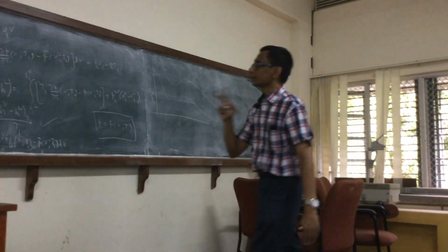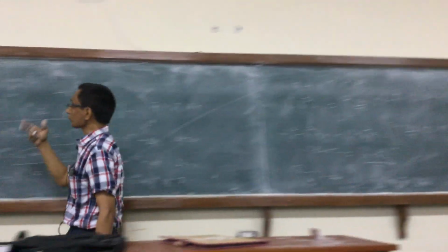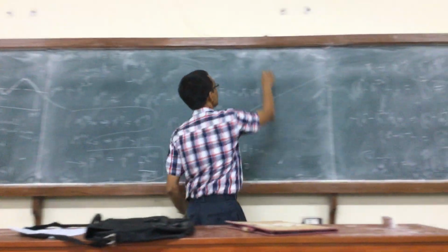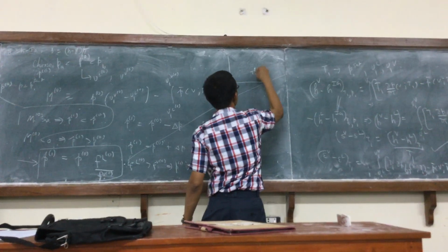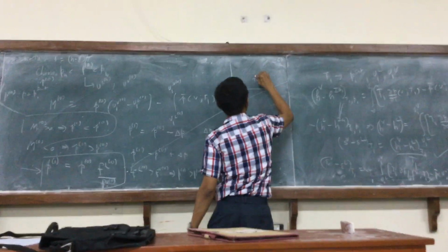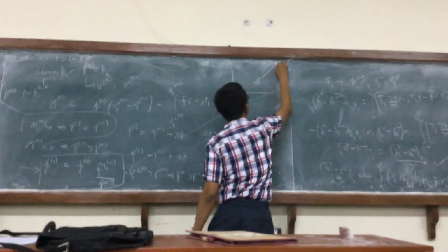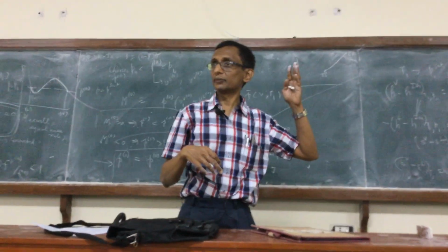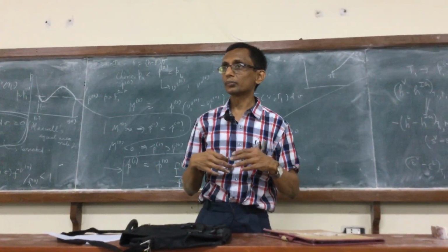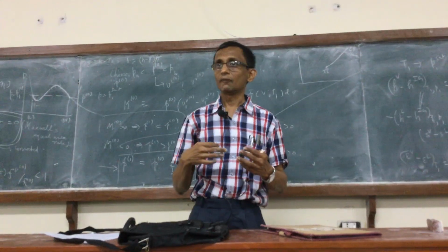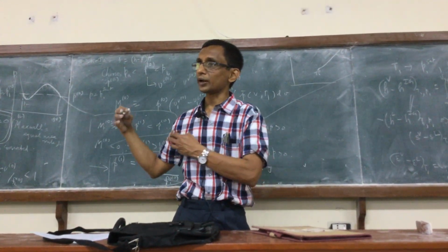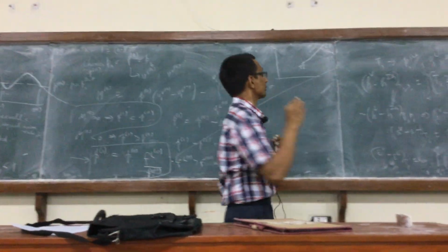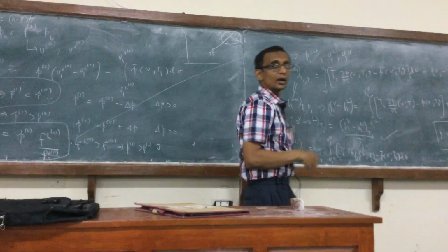Right? One thing is that these formula will be valid the closer you go to the critical temperature. Because the whole of this is to look at properties of, this is the triple point, this is the critical point, right? And we are basically tracing not only this curve but various changes like enthalpy change and so on all along this curve. So clearly, since we have pointed out that the difference between the vapor and liquid properties become closer and closer as we go towards the critical point, it will turn out that the Maxwell's rule is a good approximation for states close to the critical point.